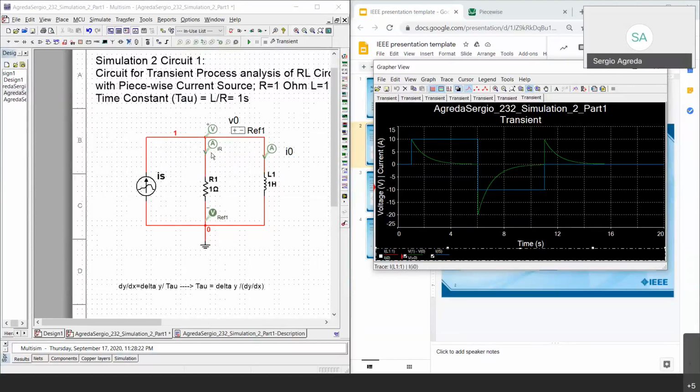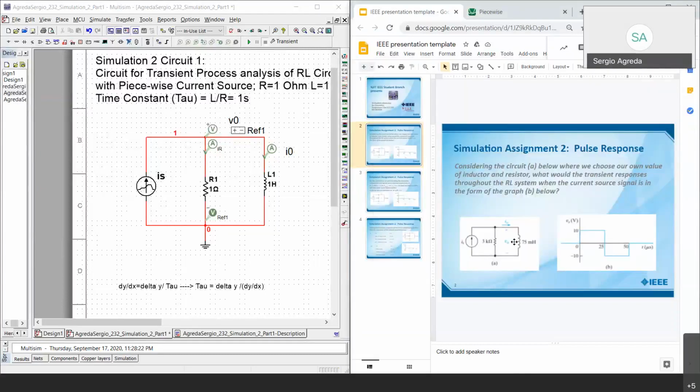Usually how I recommend people label their currents, especially time varying currents, is to make them respective to what their behaviors relate to. So this current is time varying in relation to the resistor. This one goes to I out, mainly because in the assignment, in this picture here, the current is called I out. So you just keep it the same as what the assignment describes. Same as the V out. V out is the voltage across the inductor, but actually the entire system, since this is parallel.